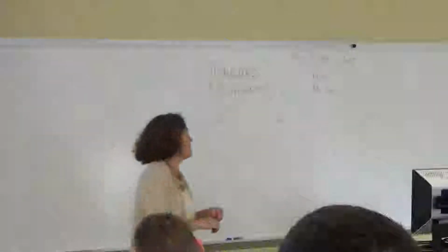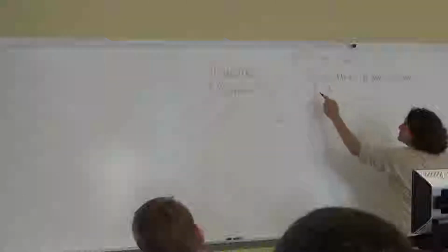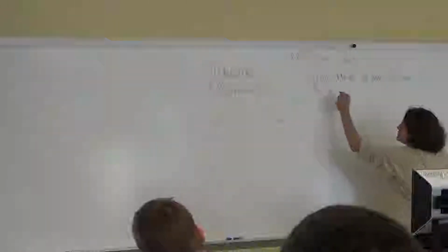We need to be comfortable with those terminologies, so that in the metric system, we always say the force first. So what's another one? Kilonewton meter. Right? How about Newton millimeter? Kilonewton millimeter. Okay, so in metric we always put the force first, but in English we put the distance first. So give me another example besides foot pound. Inch pounds. What was that new one we learned, that word for 1,000 pounds? Kip. So how about inch kip? Or a foot kip?